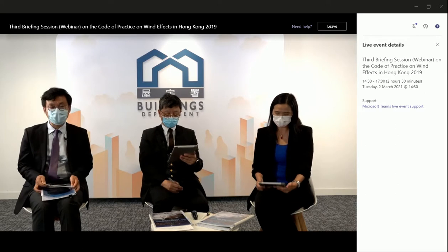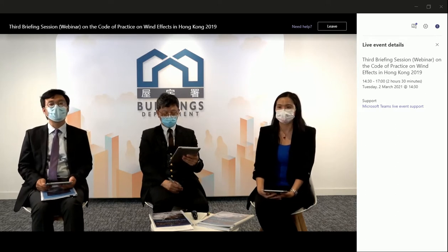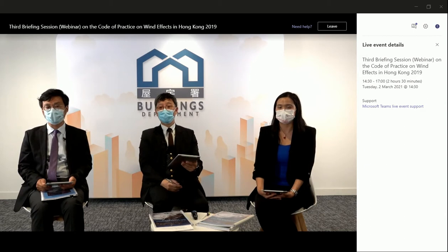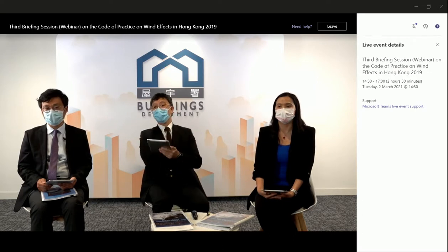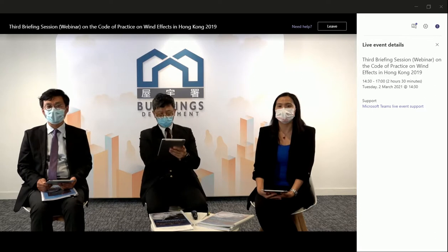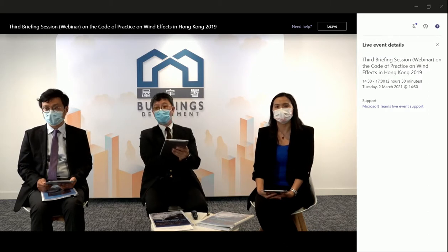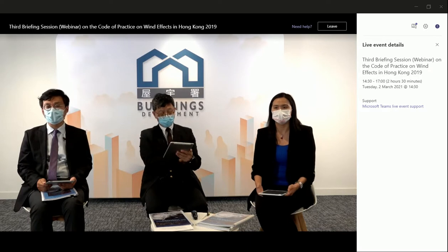Okay. For this one, actually, we have a recommendation in the EN. So in the EN, it's Appendix E. So can we show? Okay. So in Appendix E, for this multi-tower case sitting on a podium, generally it talks about if we have several towers, so they share the same podium. For this case, if there is no moving joint, how we can make sure that the critical load cases for designing the podium can be covered. So here I just talk about the general principle. The details we can refer to Appendix E in the EN.